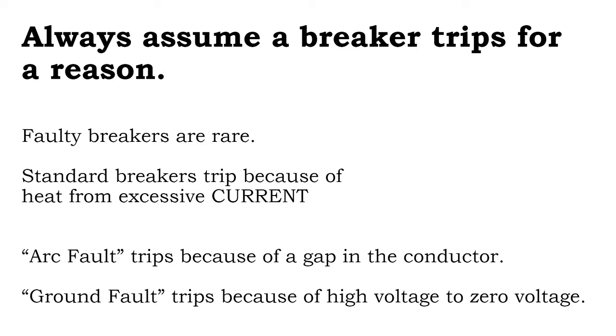So, on this inverter that broke up, I had a customer, the inverter broke up, and the arc fault on the terminal strips, the wire was stripped too long, and that caused the fault. Well, initially the breaker tripped, and the customer turned the breaker back on, and then the arc fault occurred further and did more damage to the equipment. The inverter needed to be replaced.